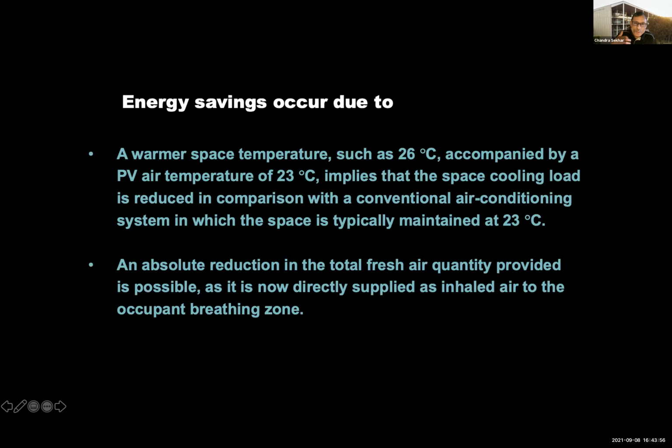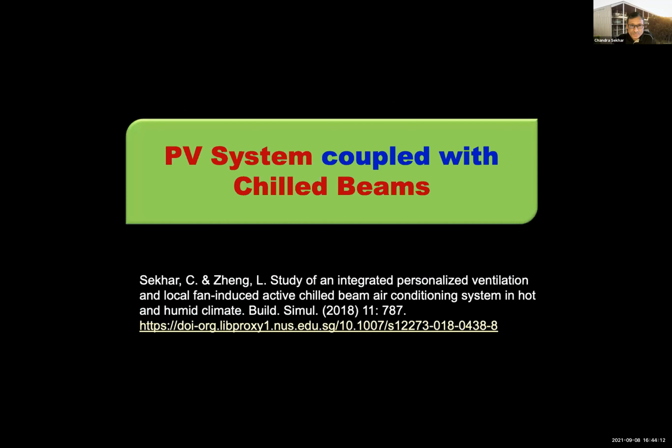When we do that, we are able to maintain your background temperatures warmer, 26 degrees or whatever, even higher, and then maintain your comfort and air quality with a small amount of personalized air being delivered at the person's breathing zone. So obviously there's energy saving from that angle as well.